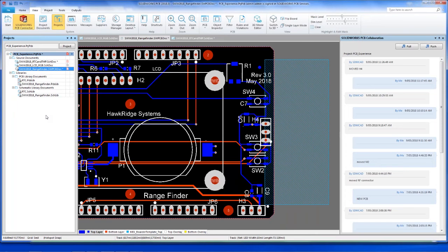You can manipulate them around. They don't become processor hungry or anything like that. So I don't view that as an issue. It just really depends on the size of your board. But if there are components that you don't want to see, let's say you only want to see your critical connectors, then you could create that variant, and then SOLIDWORKS will create a secondary configuration that you can view, and you can work on that configuration instead of the overall master assembly that's got every single model installed.